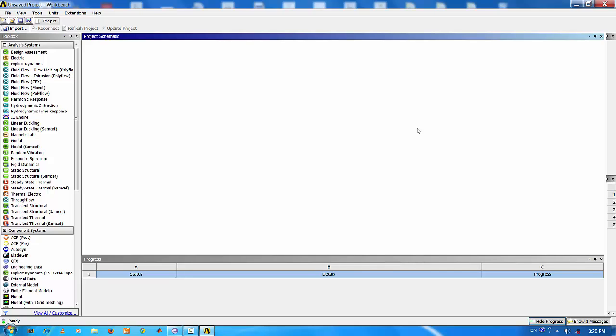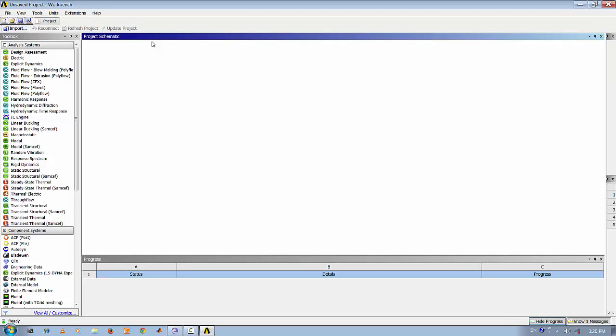This is what Ansys Workbench looks like when you open it. You can see over here, this is a project schematic window, and you can see the toolbox on the left pane. Now we will go through a simple modal analysis. Just left click on modal and place it on the standalone system. Now once you place your module on the project schematic, it opens up with a whole lot of branches. You can see engineering data, geometry, model, setup, solution, and results.